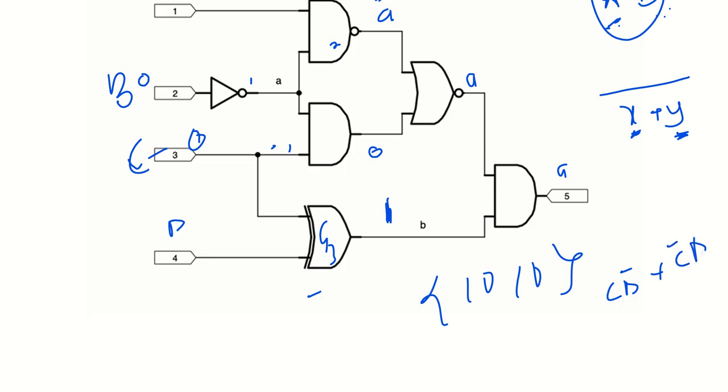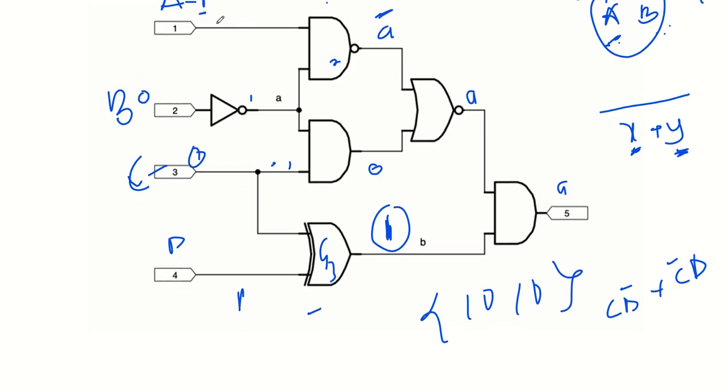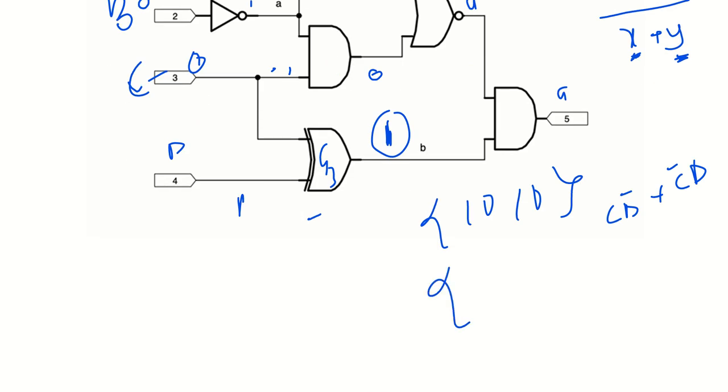The Boolean function is something like this. Now, if C is 0, then D has to be 1, to ensure that the output is 1. And that's what you get. So you realize that in the second case, the test is 1001. Now, which one to choose?